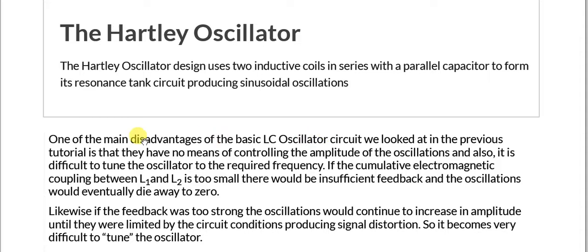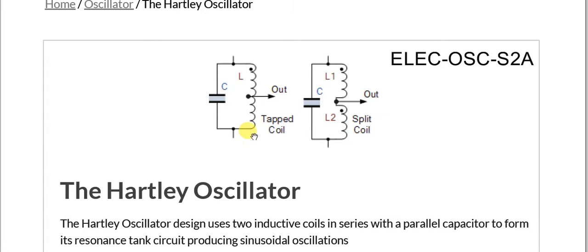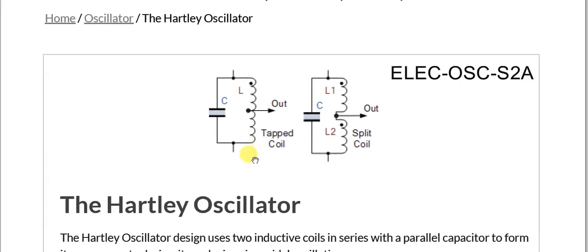The Hartley oscillator. The Hartley oscillator design uses two inductive coils in series with a parallel capacitor to form its resonance tank circuit, producing sinusoidal oscillations. Hartley was the name of the scientist who proposed or devised this circuitry.